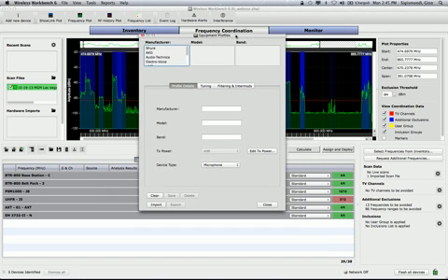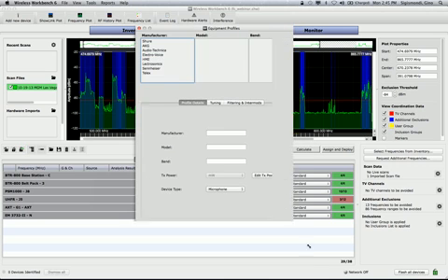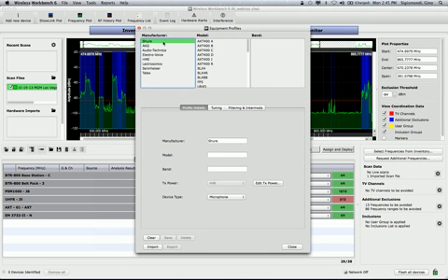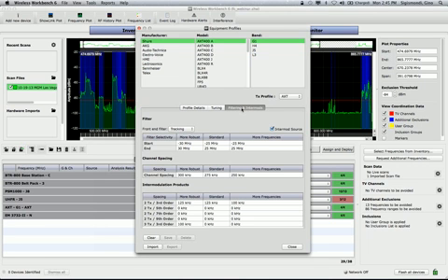So for every type of device that Wireless Workbench can coordinate frequencies for, there's some data under the hood. And this data under the hood, you can see it in the equipment profiles dialog. It defines what kind of space each one of these systems needs in the spectrum. A really linear system that Gino was describing, that might have newer components and might be more of a robust RF performer, might need less personal space than a relatively older system with older or cheaper components that might need more personal space in the spectrum.